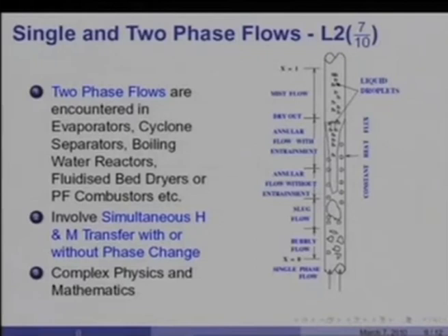So, the objective is of course to make sure that such a situation does not arise in practical equipment, and that the temperature is maintained well below the meltdown temperature of the surface. So, post dry out, you essentially have very tiny droplets which appear like a mist in an essentially vapor flow, and still further downstream all these droplets will be converted to water vapor, and the dryness fraction of steam would be 1, whereas it was 0 at the bottom of the tube.